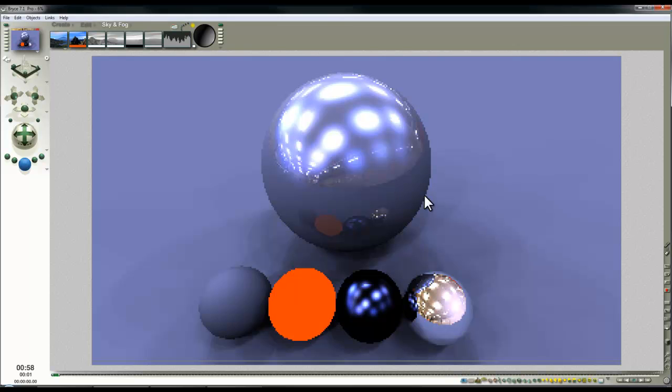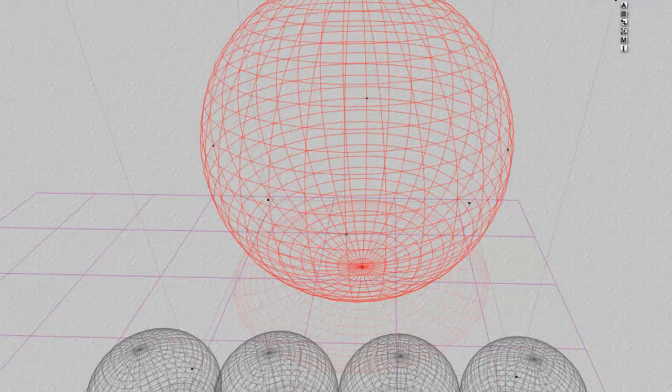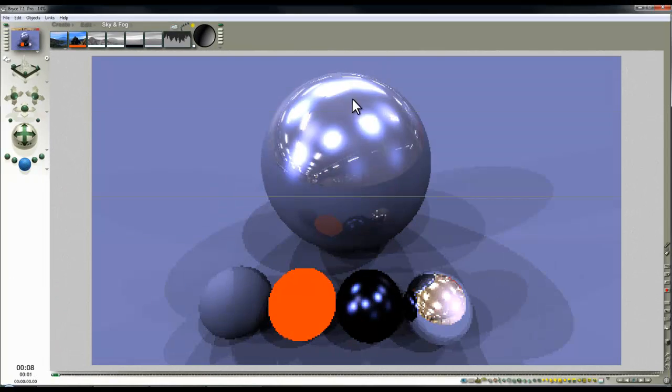so we should see a greater spread of blobs than we see in the preview. So these blobs are actually occurring, and there you can see them just on the specular response here, where the simulated light sources have been generated to light this scene, and appropriately many of them have been placed over where the fluorescent lights are in the scene. If I go back into the image-based lighting and lower the quality, then you'll see something more like you have in the preview, and the number of light sources have been reduced and there's more shadows. You can see that there's distinct shadows, and this is because it's limited to the number of light sources that it's been able to create to light this scene.